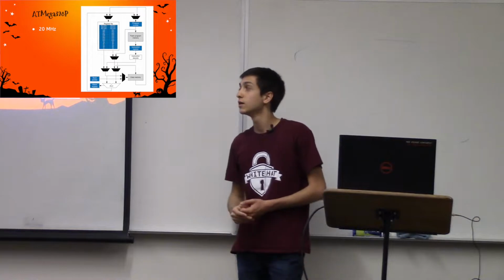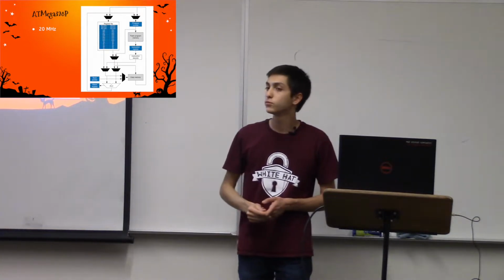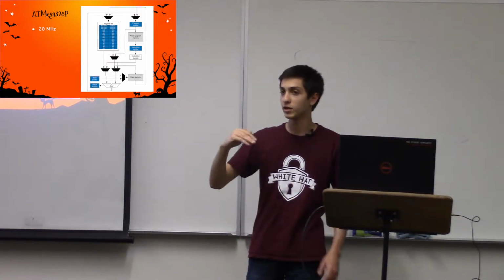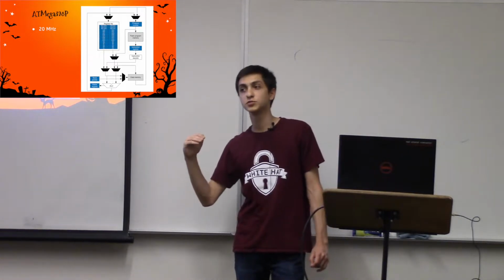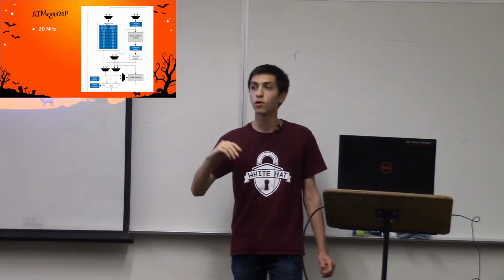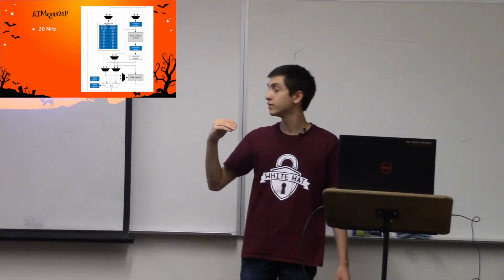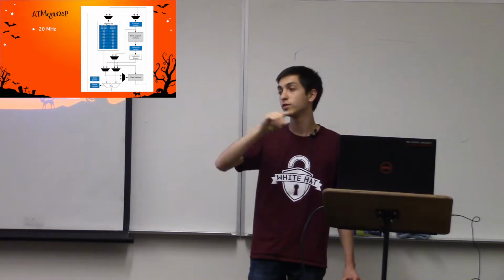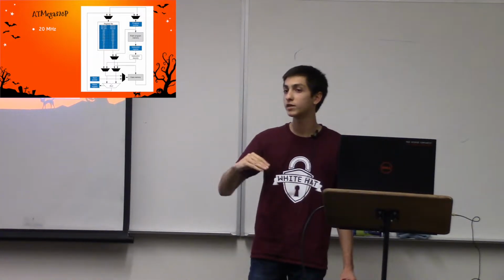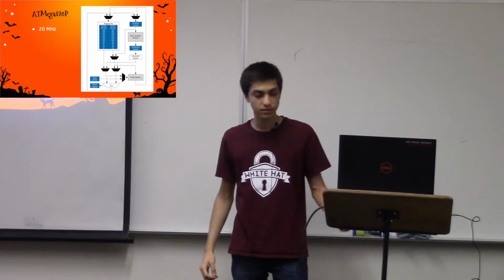skip an instruction. So this is useful, say if your program's comparing a password, and then it reaches a certain point in the program where it's like, oh, this password's wrong, I'm going to go do something. Well, on that part of the program, if you were to introduce that glitch, you can skip that instruction. Instead of going somewhere else in the program, you would go as if the password passed.